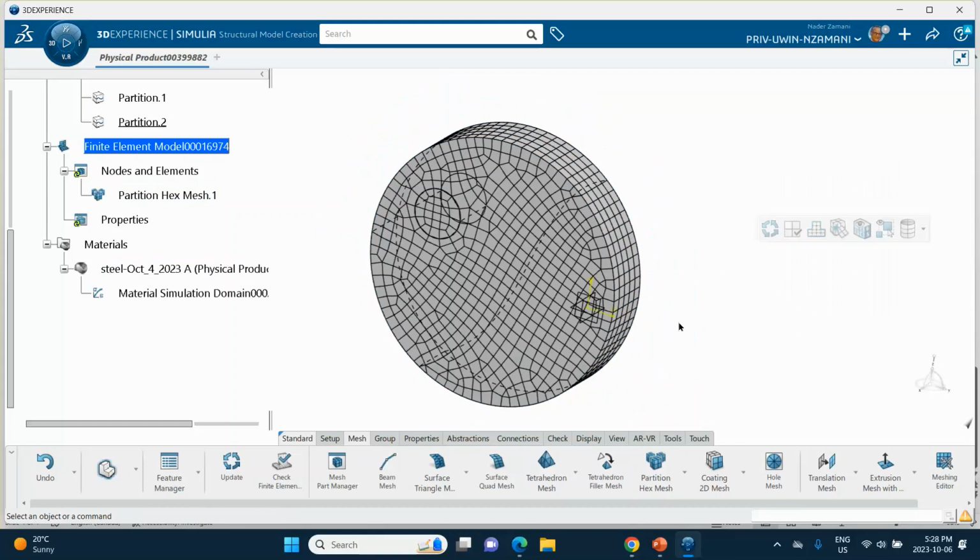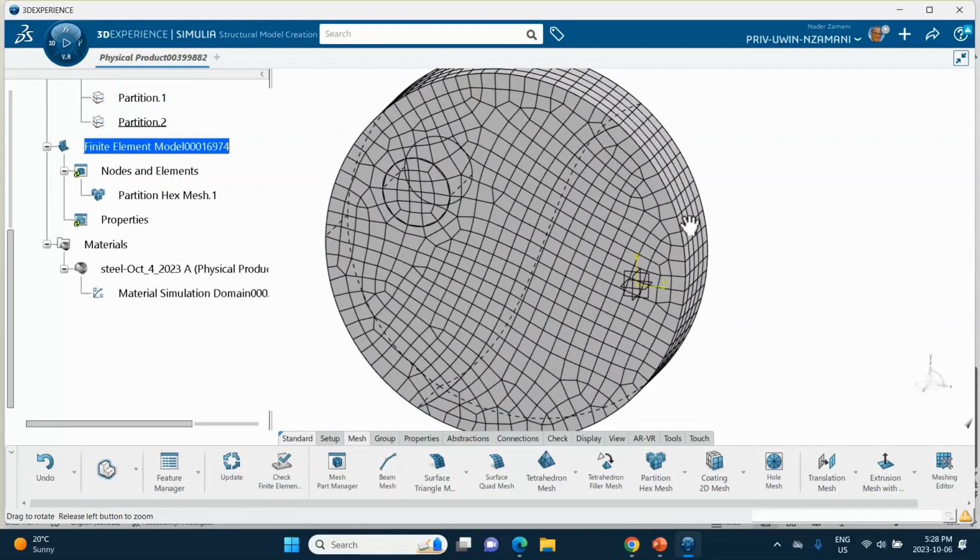You can see that. And let's go ahead and, for example, go to apply. So let's restrain these faces and apply a pressure on this side. Incidentally, you can also cut the object with surfaces, maybe planes. In fact, you can use XY, XZ, YZ planes also. Okay, so any plane will do.